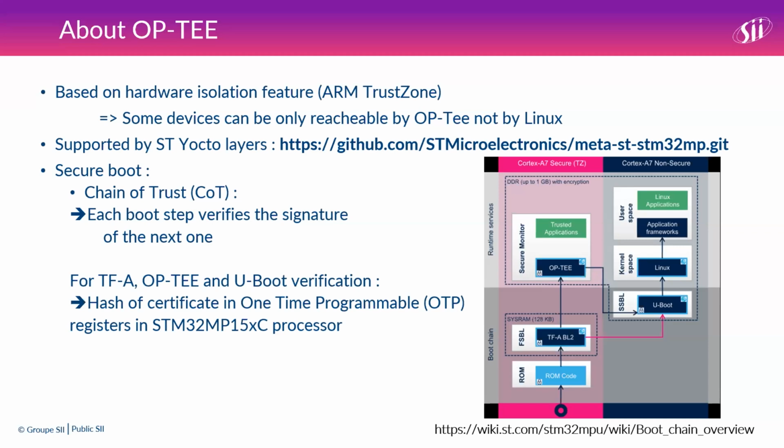For debugging, I could admit that it's a bit harder, but in fact, with the ST ecosystem, we could have a debugger directly on the M4, so it could be seen as two different products. So we could have teams working on the M4 program, debugging it, a team working on the Linux parts, and together we develop the product.